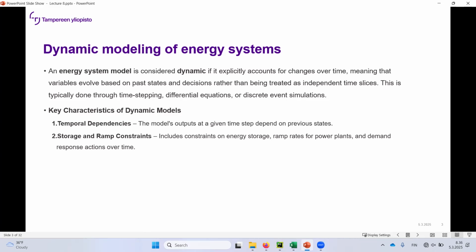Whenever you put a facility on, for example a bubbling fluidized bed, it's going to take multiple hours to ramp it up from 0 to 100. And even when it's up and running, there are ramping constraints during this hot run: whenever it's close to 100 and you ramp down, it takes a certain time to ramp down to, for example, 50%.